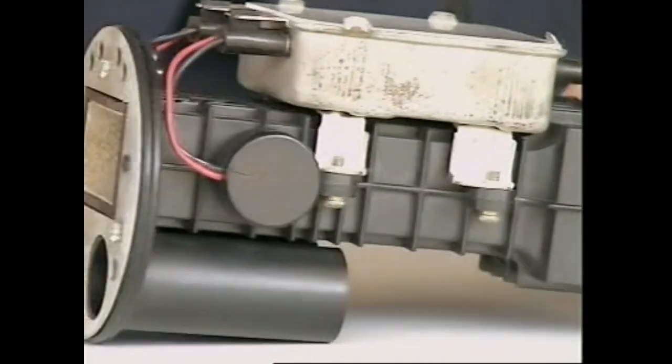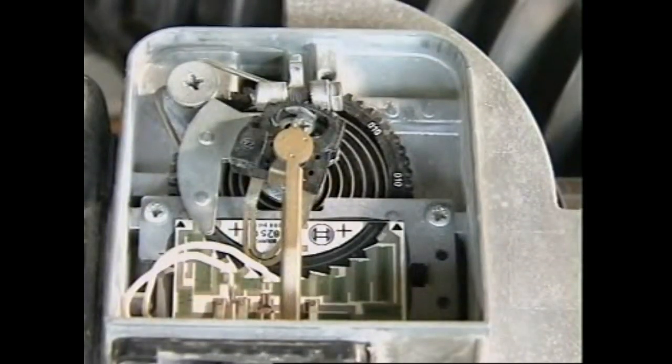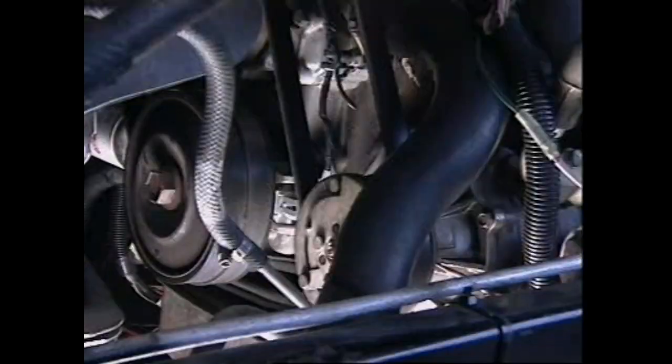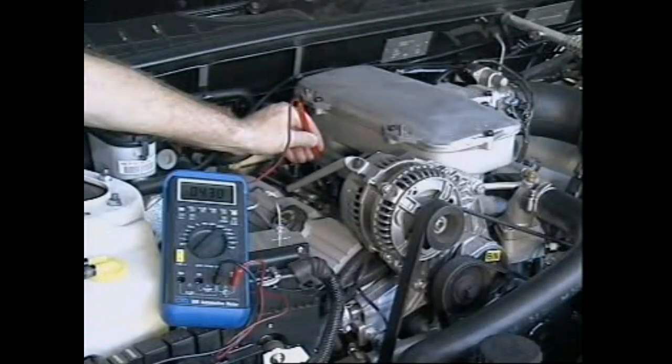Devices measuring air entering the engine send a varying electrical signal to the ECU. The signal can be a measure of the volume of air or of the manifold pressure. In both cases, this information is combined with the engine speed signal to provide the basic setting for the injector pulse width.